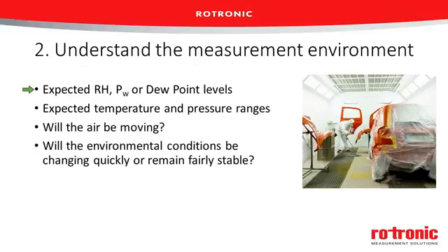Perhaps the most important thing to understand about your environment is the temperature. Temperature is very important when it comes to measuring relative humidity, and some instruments cannot measure in extreme temperatures. So if your temperature is just a place where people work, it's probably going to be a safe bet that most instruments can handle that. But if you're in a more extreme condition where it's very cold or very hot, then that will very much affect the performance of the instrument you choose.